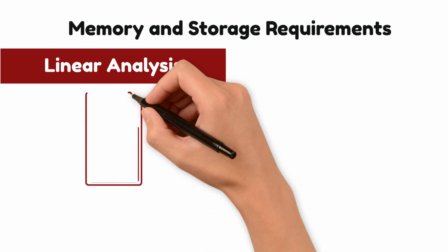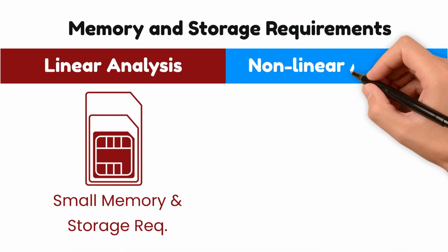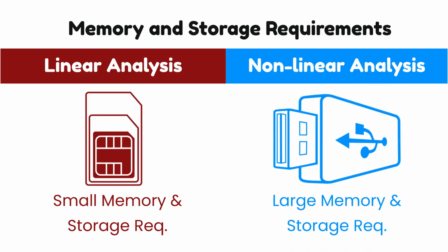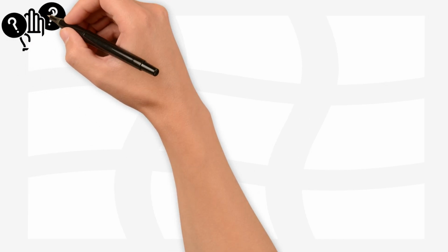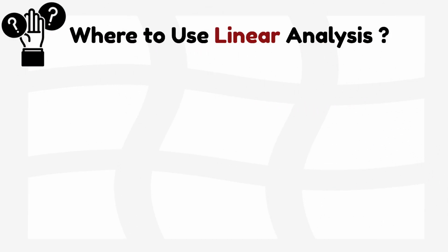It needs less memory and storage since the system is solved only once. But nonlinear analysis is much heavier. Each iteration, every load step, and every geometry update adds to the memory and file size, making it far more data intensive. So now that we have seen how linear and nonlinear analysis differ, let's talk about when to use